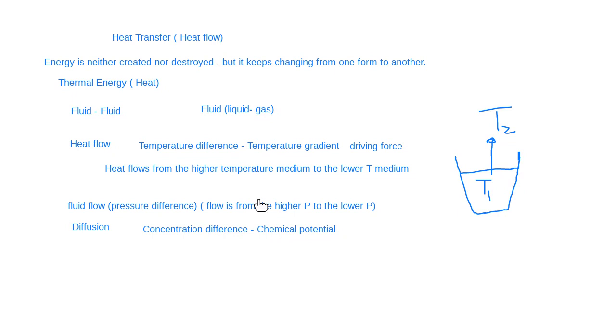medium to another medium. Now let's remember guys one important thing, that in heat exchangers the heat transfer takes place between the fluids while both fluids are mechanically isolated from each other. There is no mixing between the fluids. Okay, so as an example, we have seen in shell and tube heat exchangers, one of the fluids is in the shell side and the other fluid is in the tube side. Okay, there is no mixing between the fluids. Okay, so that is very important, guys, to notice.